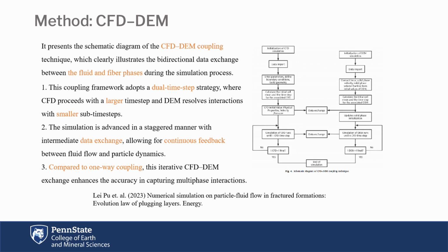The method we use is the CFD and DEM coupling technique between the fluid and fiber phases during the simulation process, which we can see from the figure. It shows a dual time step strategy. The CFD method has a larger time step, and the DEM resolves interactions with smaller sub-time steps.